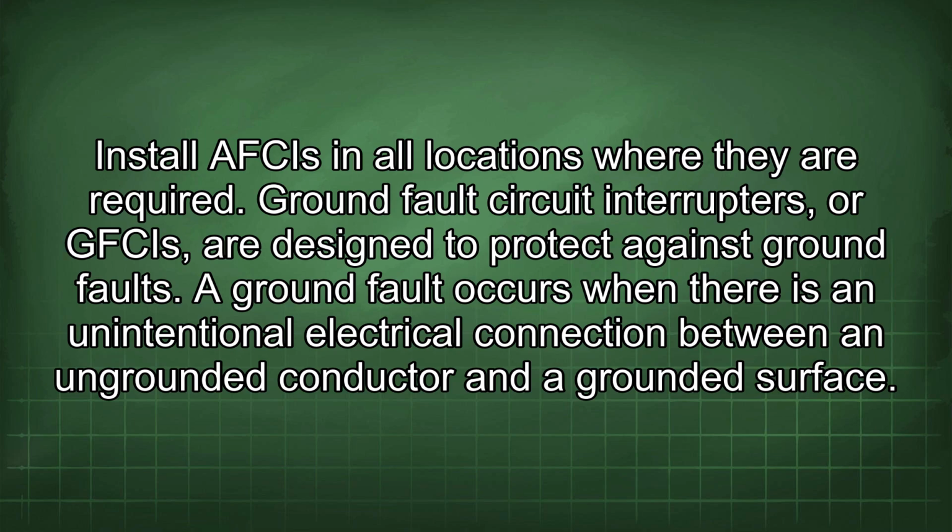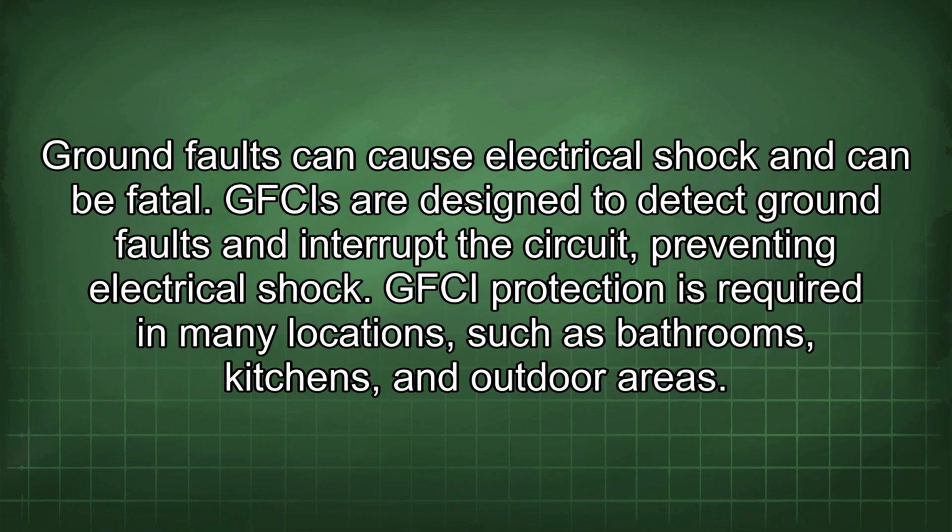Ground fault circuit interrupters, or GFCIs, are designed to protect against ground faults. A ground fault occurs when there is an unintentional electrical connection between an ungrounded conductor and a grounded surface. Ground faults can cause electrical shock and can be fatal. GFCIs are designed to detect ground faults and interrupt the circuit, preventing electrical shock.